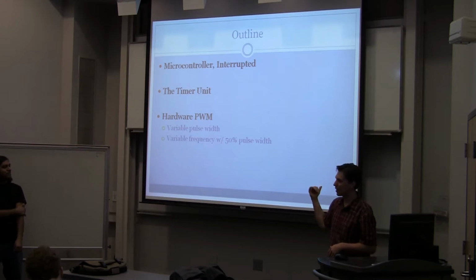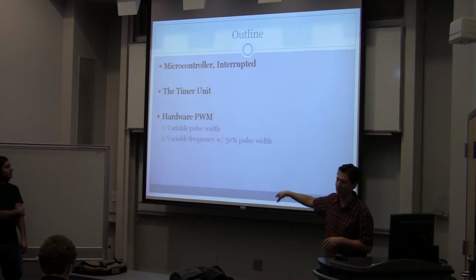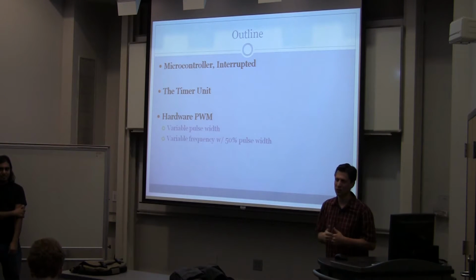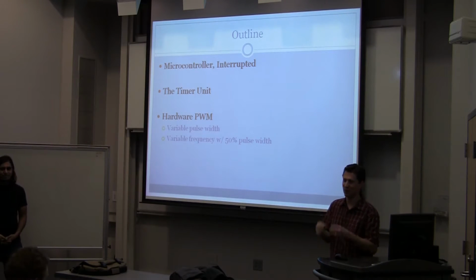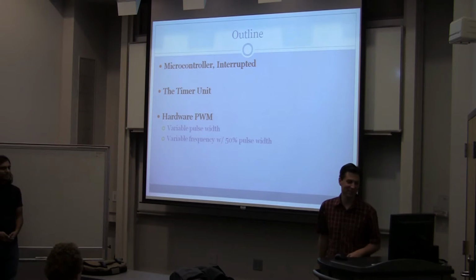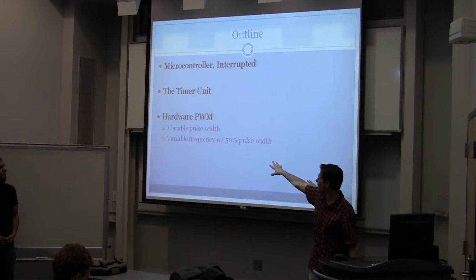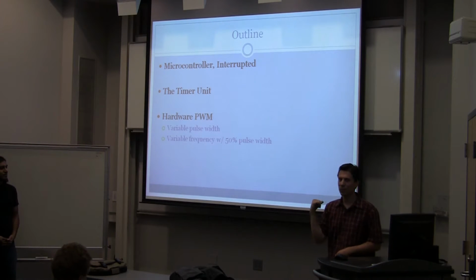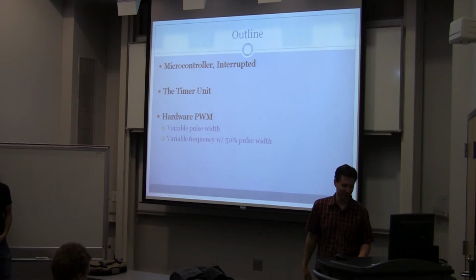We're going to talk about timers, which are also really good ways to do things at a set frequency, or to create things like pulse width modulated signals, which are great for controlling motors, servos, very cool LEDs that don't actually blind you because you can set them to half power, and also buzzers. So today we're going to talk mostly about using PWM to control motors and buzzers. I don't expect that we'll have time to get to LEDs and servos, but we'll do that on Wednesday, along with sleep, which you all need more.